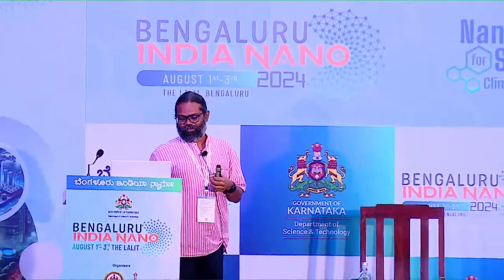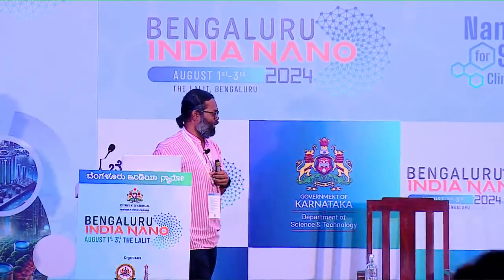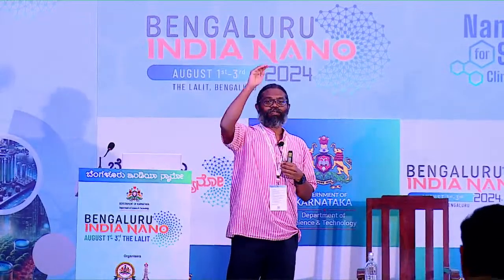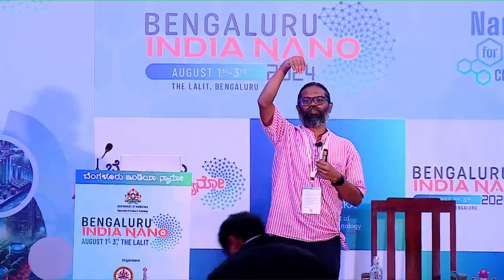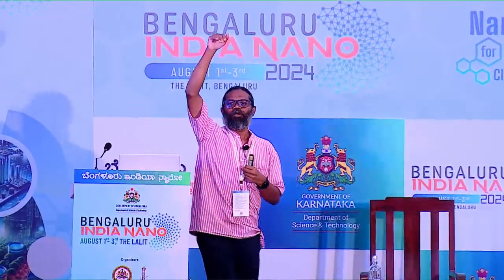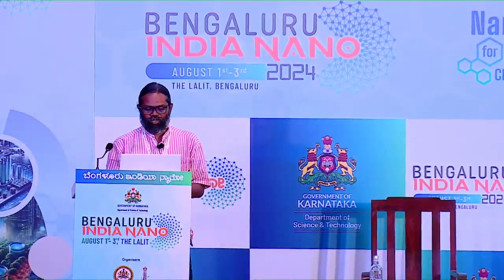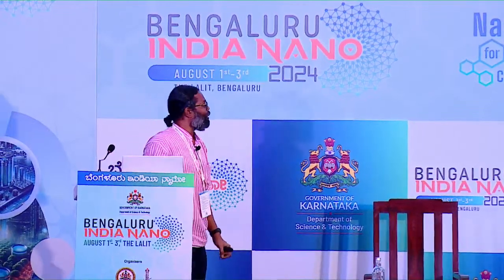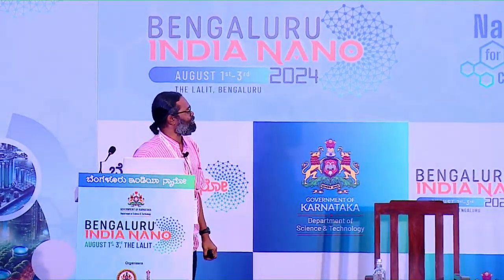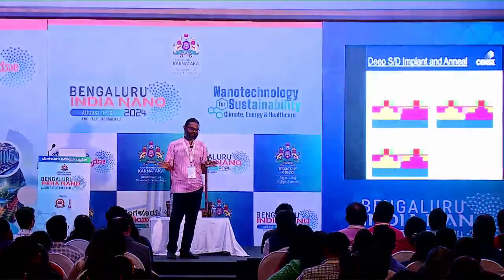And you can use different energies. You can see here this is 15 kilovolts and this is 5 kilovolts, right? And that will tell you how deep you are going into the silicon. If you use less energy, it will stay on the top. If you use very high energy, it will go deep in, okay? So we call that source drain doping. Once you do that, you start to create this transistor along with the source and drain sitting next to it, okay? So now you actually have a transistor.